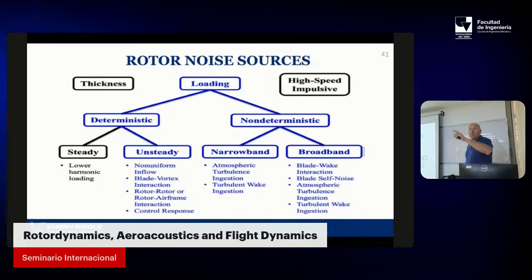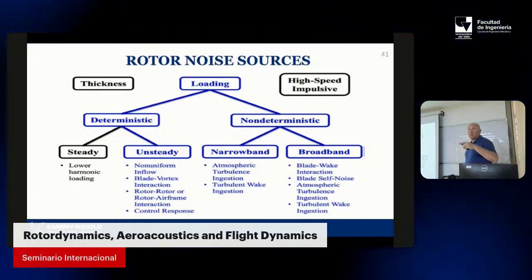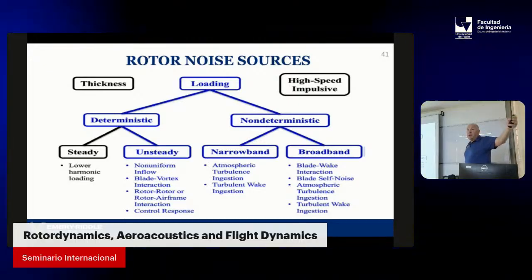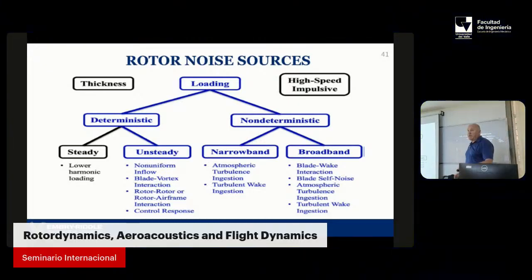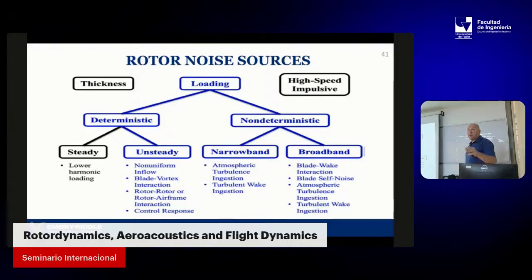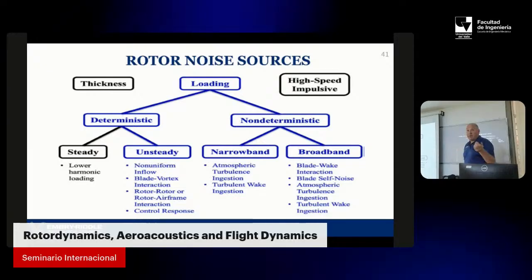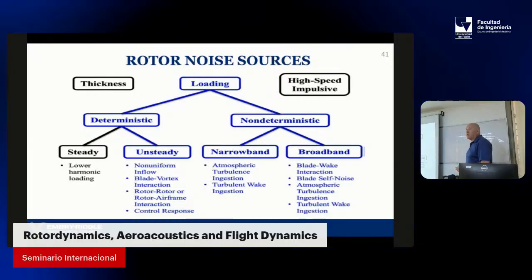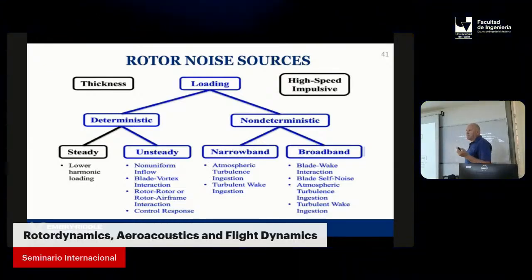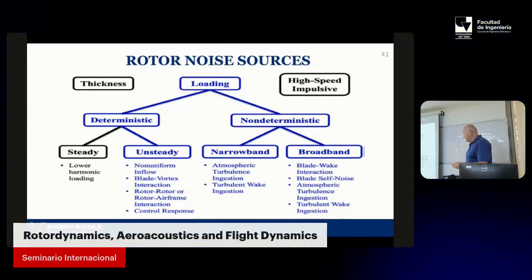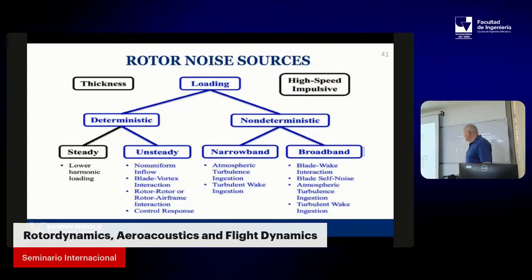Also for the turboprops, by the way. If you look at the turboprop, the same thing. You typically will see this single BPF with maybe other harmonics, but that will be the primary thing for turboprop engines, right? Which are typically on small aircraft, but still much used. Well, general aircraft, right? Same thing. The turboprop or prop fan or any of those combinations, or just propeller. Or piston.